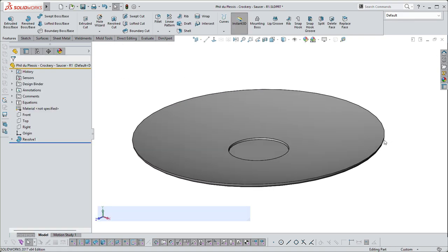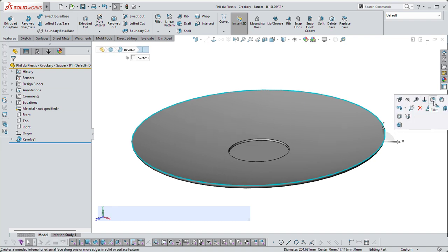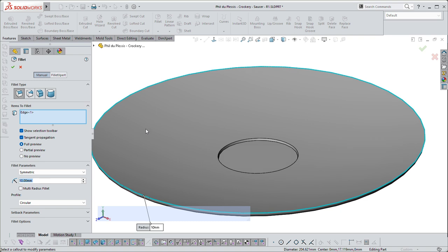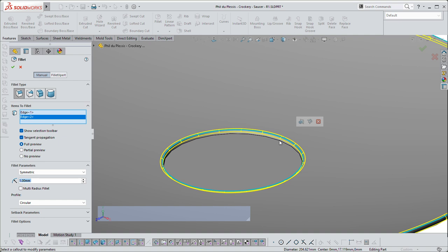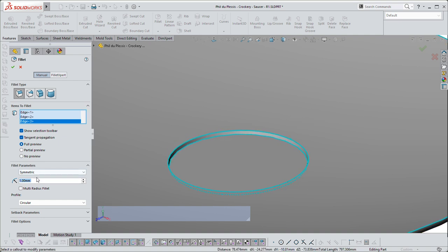And then I'm just going to fillet that with, or say 1. Let's try 1. 1 will do. Let's see if we can get these to do the same. Might not work with that little bit. No, it's too big. So 0.7. Yeah, it'll do it.